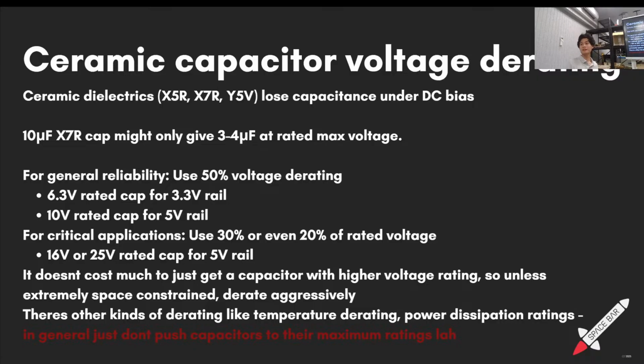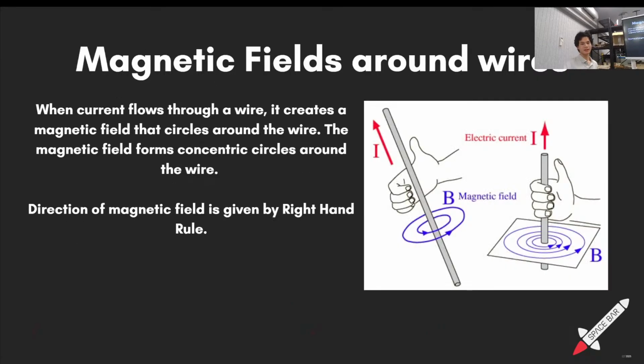Physical damage. The ceramic capacitor is ceramic, so it is brittle. If you flex it or mechanically stress it, it can just break. Also, the ceramic is piezoelectric, which is annoying because it vibrates. Not a lot, but enough to matter for very sensitive applications. It doesn't matter unless you have an accelerometer or vibration sensor on your circuit. Should have made a whole slide for that.